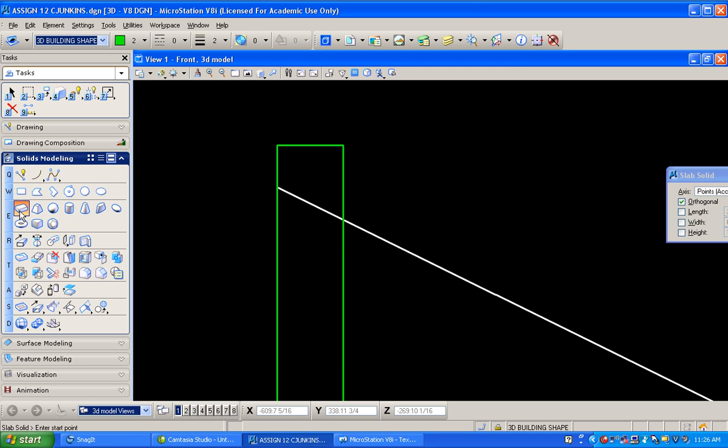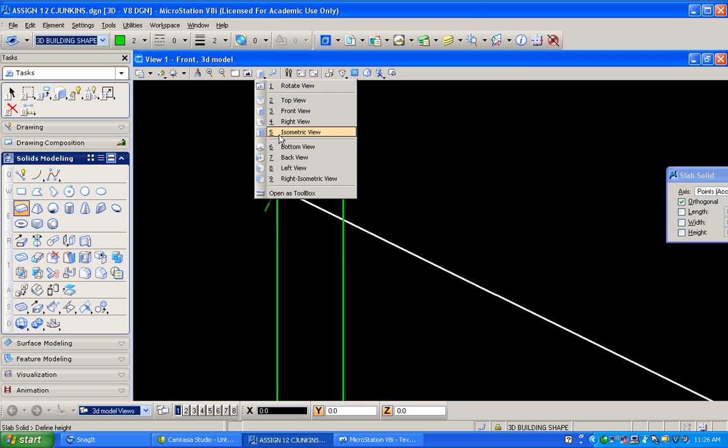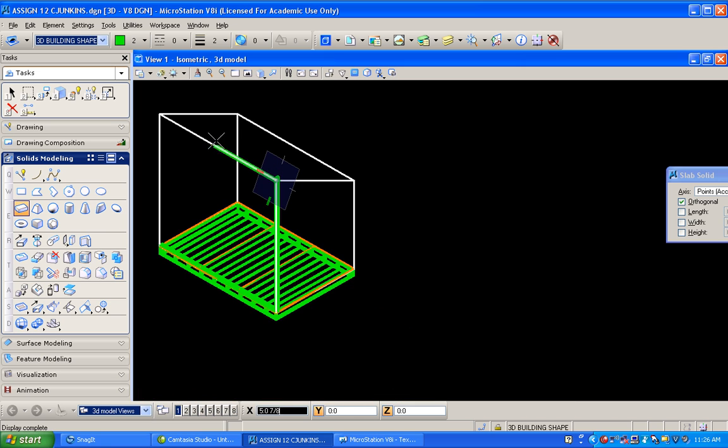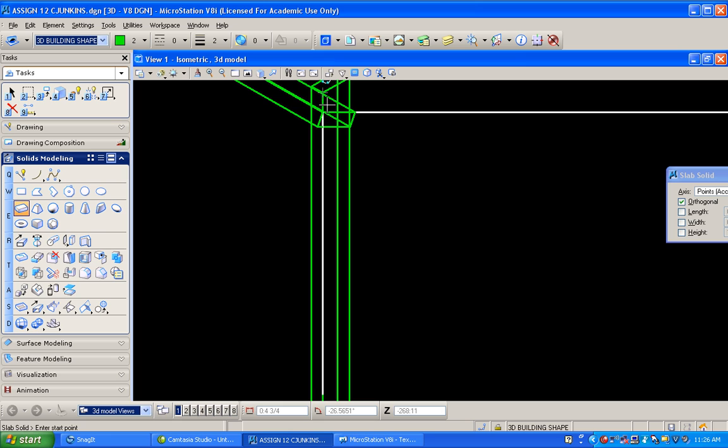So if we do that, we can take our smart line or our place block tool, 3-dimensional. I'm going to hit F for front, and I'll just go spacebar N, because I don't really care what the width is on this. We're going to rip it anyway. Just left click here, pull it down, colon 1.5, and then see if we can roll it to an isometric, and there we go. And we're just going to pull this out beyond the end here. And you can see that that was right on this edge, so that's where we want it.